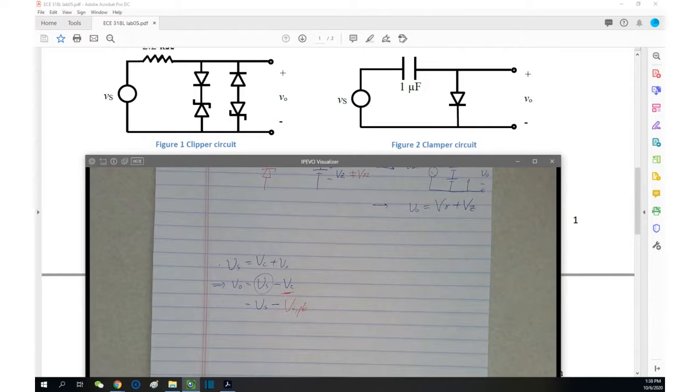I don't think I understand. If we use figure 2, the clamper circuit, and between the Vs and the capacitor we add resistors to bring us down to the voltage peak that the capacitor sees at 12 volts, is that how we would charge a 12-volt battery, or would we need more diodes in there? What is your AC source? The wall in my house. The wall? No. You can't do that. You need to reduce the AC peak value to be the same as the battery voltage. So would I just use resistors to do that? A resistor can only limit the current.